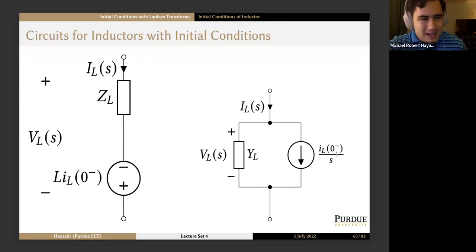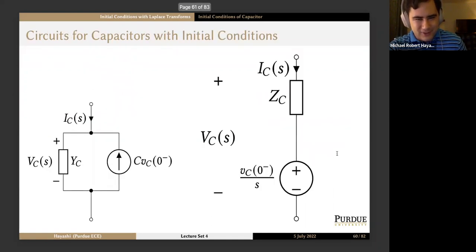And you're like, how am I possibly going to remember this? Well, remember, capacitors are voltage things. Capacitors like being in series with things. Well, voltages, we like to deal with voltages in series because they just stack and add by KVL. So remember, we'll have step function initial conditions that work together.